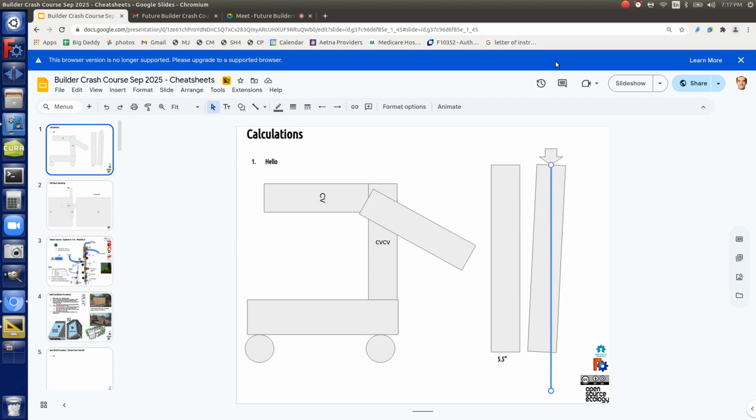So here, if we had the force going down like that, it's acting through the middle. Okay, cool, great. Here, what you're seeing, you've got a problem. It's only this much of the wood that is actually supporting it. All this stuff is doing nothing. It's like it didn't exist there. It's doing something because it's actually connected to the rest of the wood, so those fibers of wood are holding it, but you're literally starting to shear those fibers of wood. Okay, this is getting dangerous.